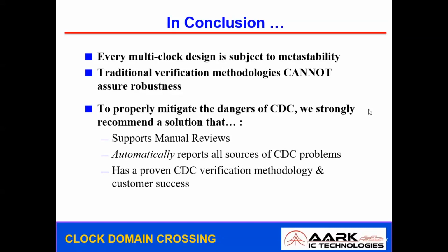Thank you, sir. Can we use an asynchronous FIFO to rectify the CDC problems? Exactly, as I mentioned earlier, there are two different protocols: handshaking and FIFO. This FIFO is an asynchronous one. Synchronous FIFOs will not work for addressing these issues. Only asynchronous FIFOs will work, because they operate with a different write clock frequency domain and read clock frequency domain. Therefore, we can make use of asynchronous FIFOs to address these CDC issues.